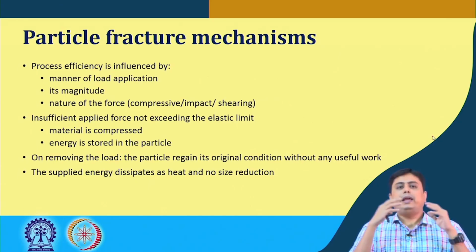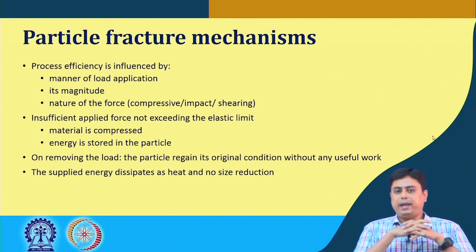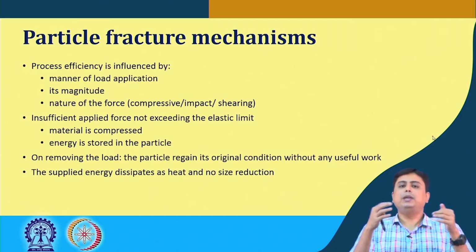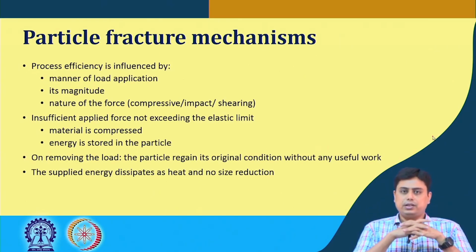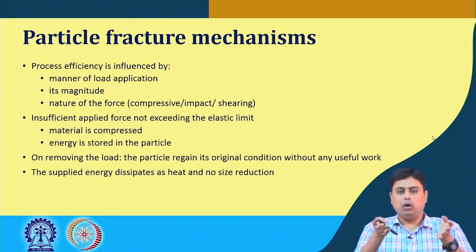So, when insufficient force is applied that does not exceed the elastic limit, size reduction is not happening; the material is compressed and the energy is stored in the particle. What does this elastic limit mean? If we remove that load, the solid regains its original condition without any useful work.